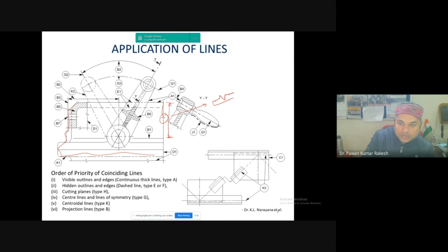It means the drawing size is increased. Like this way you can do it. If you do the hatching, right, the spacing between one line and the other in the section is 0.7 mm. Generally we follow this for hatching applications, right? So some zigzag line is there. Depending on this line, you can then mark the center lines, right? Here also you can see these dimensions. The thin line we are using for enlarged applications. So there is a big part, right? In a casting with a big part, in that case also we are able to represent it with different line dimensions.